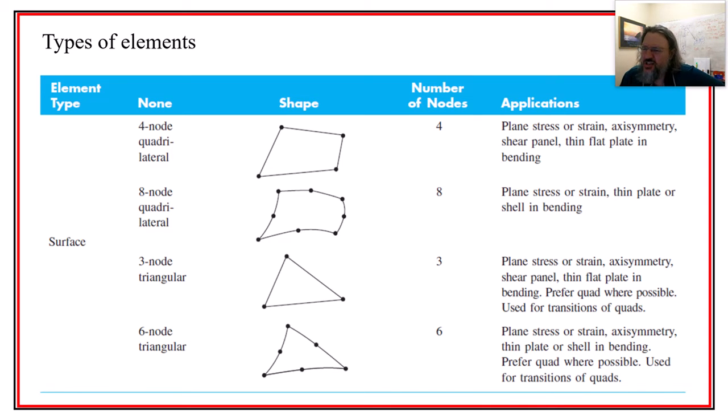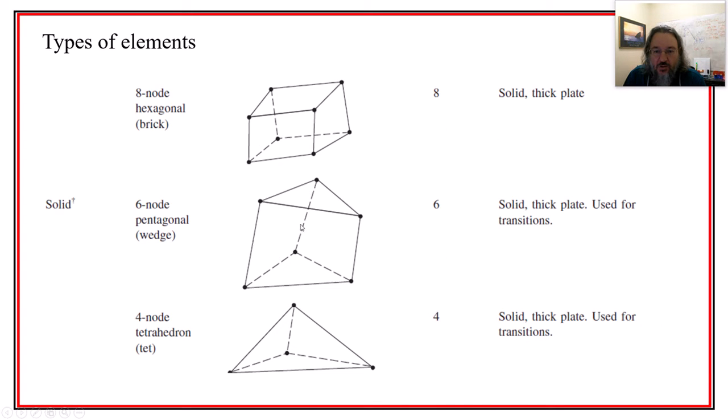But now, because the triangle elements were too stiff was basically the idea, by putting in mid-side nodes we're able to adapt that. But we still want to be careful when we mesh something not to get too thin and narrow of a triangle, right? We want as nice and symmetric as we can. We just don't want these weird shaped elements because they will give us bad results. A lot of times it's because they're too stiff. So these mid-side nodes really did help.